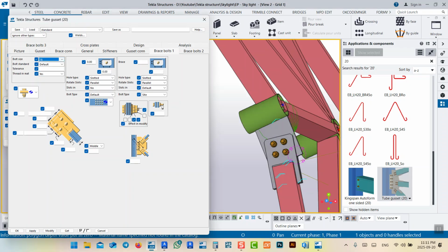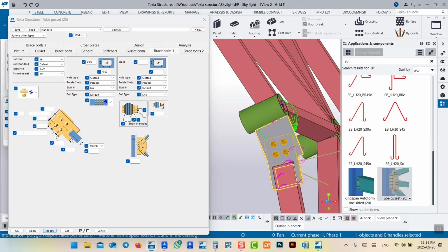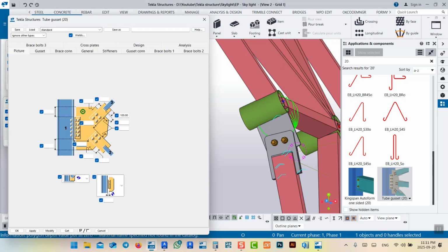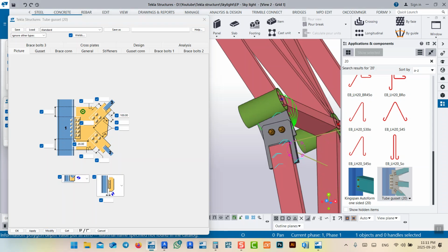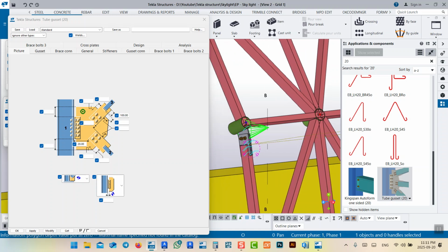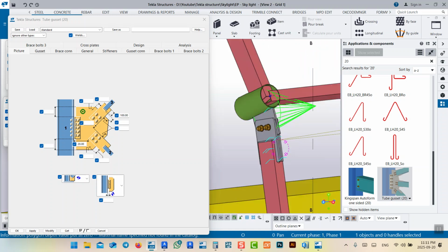Anyhow, I will go back to the 60 millimeter and 2 millimeter as a tolerance, and I have this one maybe 40 by 40, and I have one column of bolts, and I'll not change these two. I'll go back here. Maybe this one has a 30 or 20, maybe 20. I think is quite enough. I'll see this one here, because maybe if it clashes, I will increase this number.